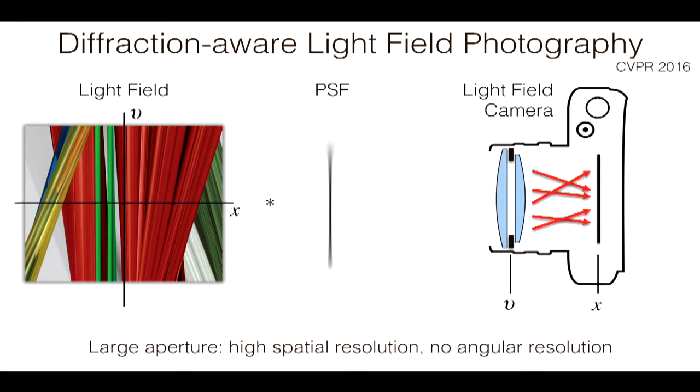So how are you going to do that? It's impossible. And the fundamental limit is the diffraction limit in this case, because even if you could make a microlens that's extremely small and still have pixels that are very small underneath, you won't be able to resolve any of that information because it's under the diffraction limit then. So we came up with a different idea.